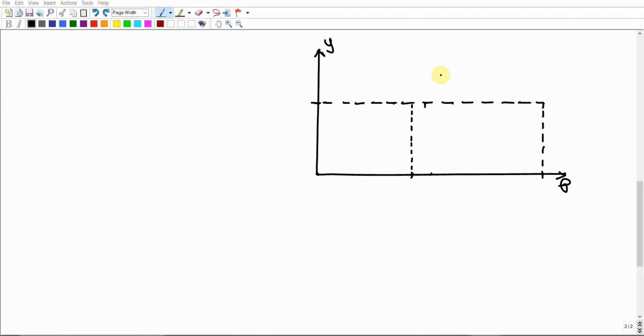And do the same for the return period, which is also 150 degrees. If you divide 150 by 30, this gives us 5, which is equivalent to 5 centimeters. So you're just gonna measure another 5 centimeters, starting from this point, in this direction. You're gonna end up with a point here. So this is gonna be the 5 centimeters. Then you're just gonna draw another vertical line from this point to define the return period.